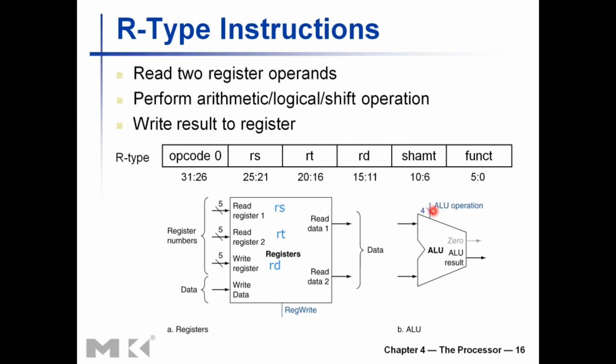And for the ALU operation, we need to generate a control signal using the function field. Whether it's an add operation or subtract operation, based on the function given here. Note that this is a 6-bit field, bit 0 to bit 5, and we are sending a 4-bit ALU operation, indicating that the ALU can have 2 to the power 4 different functional units, different functionalities.